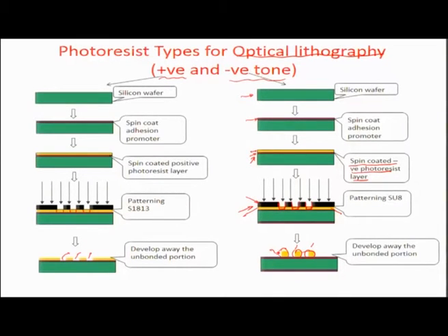Let us now go back to our problem of how different kinds of lithography can be carried out. So, it is all about how you are placing this mask. This mask can be placed on the surface in close proximity with the surface, but the disadvantage of such an orientation is that when you want to do photolithography between alternate wafers and alternate runs, you need to pull out the mask, which may damage the surface you are actually working on. So, that is one of the fallouts of this particular process.